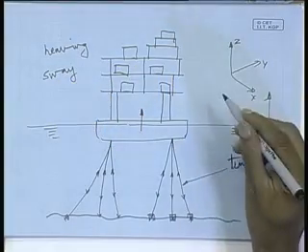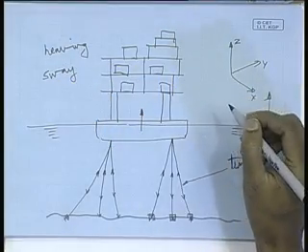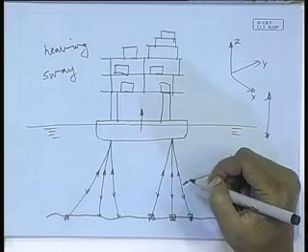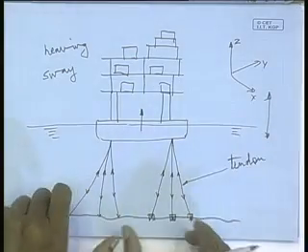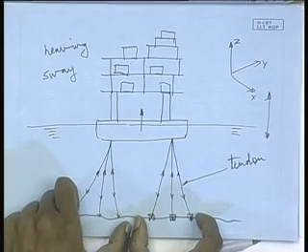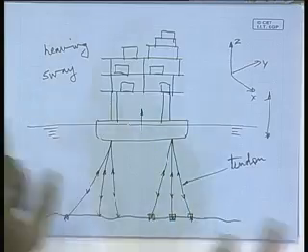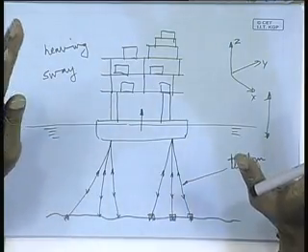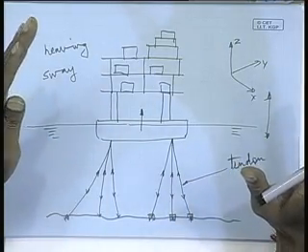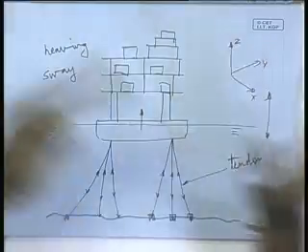And here, thereby your heaving motions are minimized, and the deployment of tendons is done in such a fashion that your swaying is also within a permissible limit, because you cannot allow it to sway kilometers, definitely not, right. Whatever is the permissible movement is possible, it's limited.